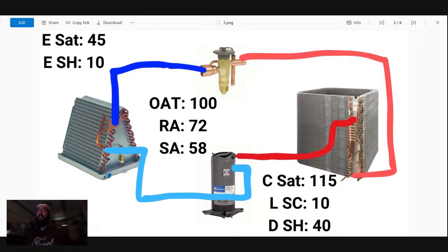We've got to be careful with the rules of thumb. But yes, in this particular case, I designed this scenario to be a high fan speed diagnosis causing high humidity, the humidity being the symptom. So by lowering that fan speed, we're slowing the air down, we're processing it better, getting the humidity out, and the customer's perfectly happy at that stage. Good job, guys.